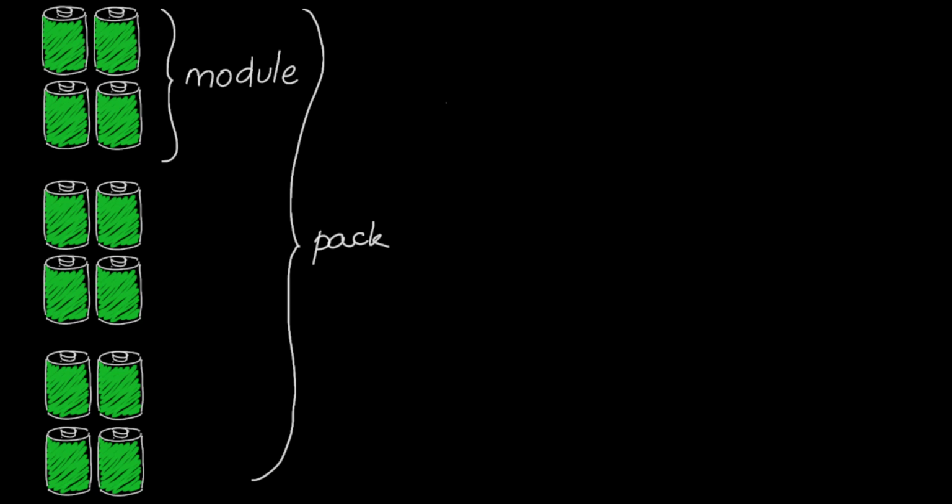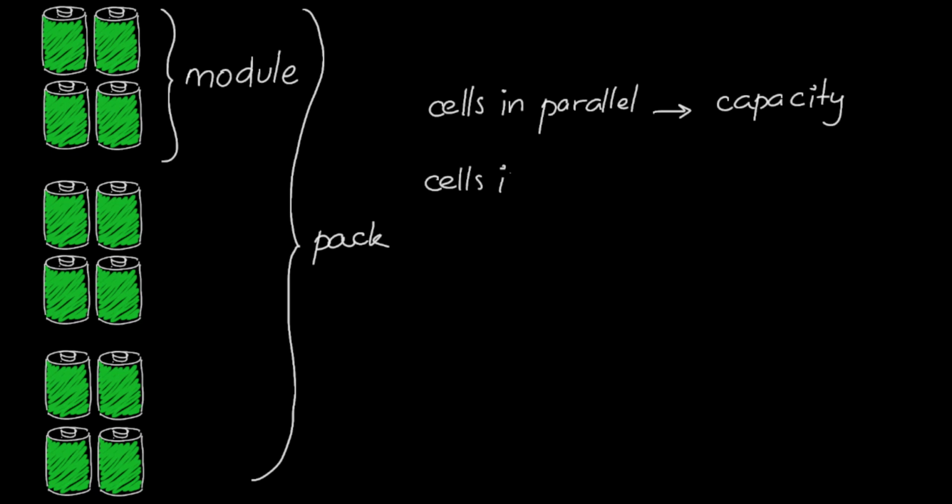Only in most unusual situations do we need only one cell. Typically, we connect cells in series and parallel in an assembly called a module, and the connection of modules make up a pack. Connecting cells in parallel builds up capacity, and connecting cells in series builds up voltage. The specifics of the application will help us determine the series and parallel count.